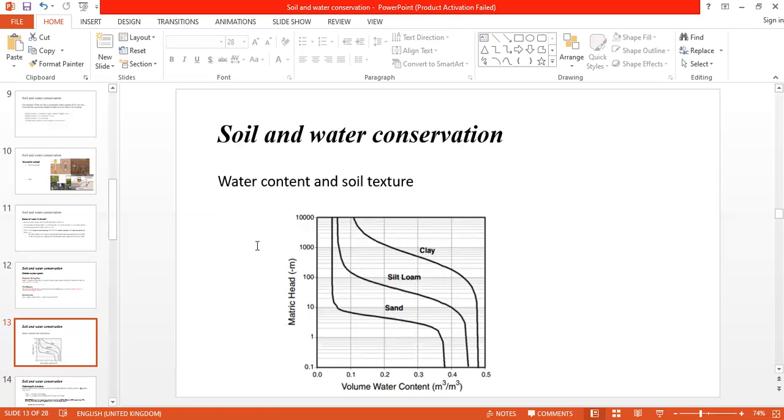What we've done is we've established for each field what we call the TAM, total available moisture, through soil laboratory tests. So we know that for field A, to reach field capacity, or total available moisture, it's maybe 90 millimeters of water or so.